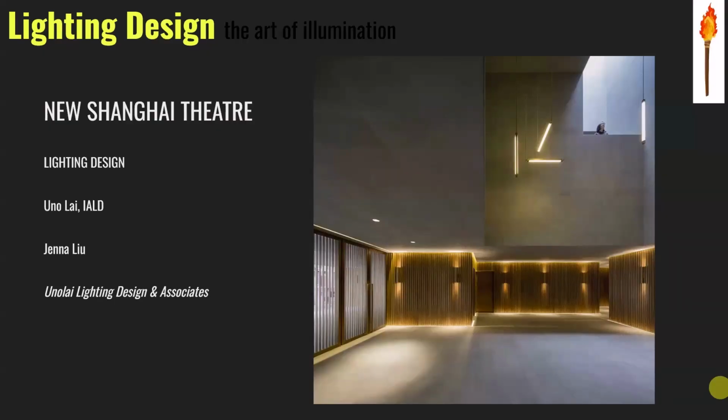You have lighting around the perimeter on the top and bottom. You have the sconces creating this rhythm along this other vertical repetition. You have some downlights, so you're lighting up the floor where the entrance is. You need to light the space for the people. You have daylight coming down from above diffused, and then you have the interesting decorative lights that also add a little bit more to the space, right? So it kind of draws you.